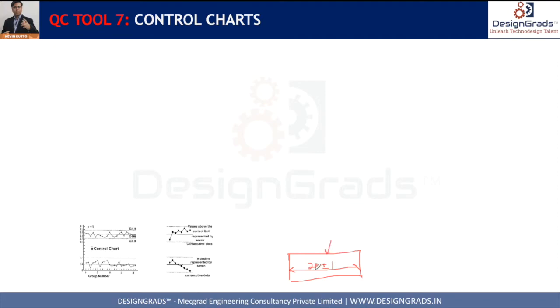That means I'm going to get a lot of dimensions, and by studying these dimensions I can understand whether this process is in control or not, because in any given process there will be a lot of factors that affect it. So there will be manufacturing variation, material variation, worker variation, inspector variation, environmental variation, right? The measuring equipment variation, tool setup variation.